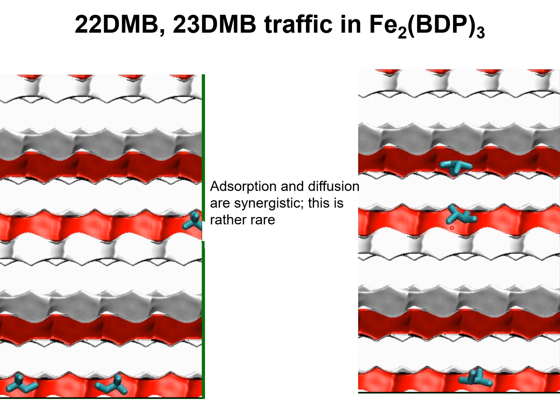The combination of poor adsorption strengths and low diffusivity values makes for earlier breakthroughs in fixed bed adsorbers, and this is desirable from a process standpoint, making Fe2(BDP)3 a viable candidate for commercial use.